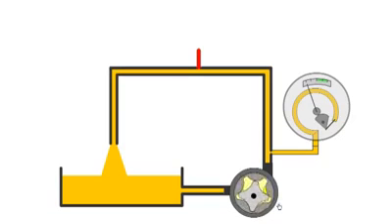Pressure is created when the flow of oil is restricted. We use a Bourdon pressure gauge to indicate oil pressure. When pressure in the tube increases, it tends to straighten, and this change in dimensions is amplified by the linkage and gears and displayed by the pointer on the dial. If we close the valve, the flow of oil is restricted and we start to build pressure.